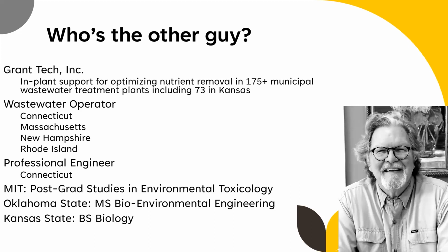There's been a big push in Connecticut, going back 25 years, for Long Island Sound nutrient removal. So in operating these little plants, they weren't operating that well for nutrient removal. And I had to educate myself on how to get first nitrogen removal and then later phosphorus removal out of all kinds of different technologies.